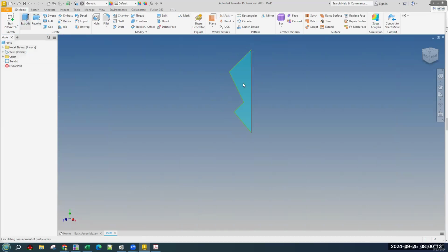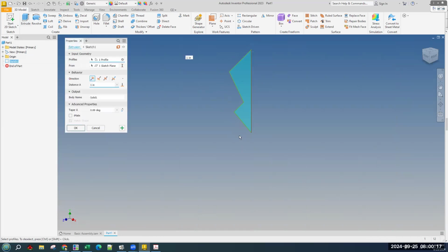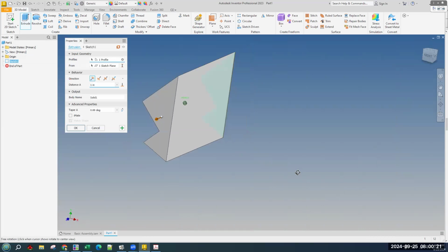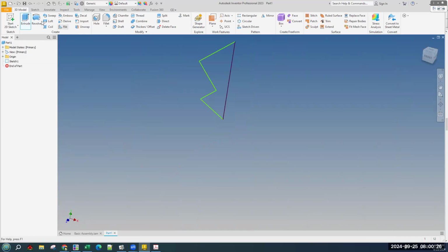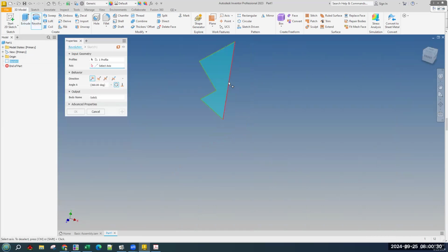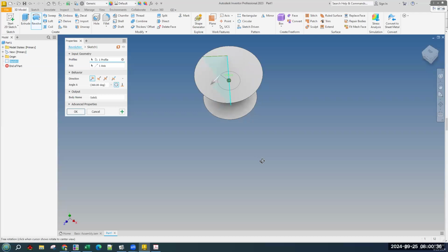It's going to look like this shape, but pushed through a toothpaste tube, or like a Play-Doh extruder, which is what those things are called. It'll make that shape. But if we use the revolve, we choose it like we're going to extrude, but then we choose an axis as a second thing. It will spin around it and make the shape that way.